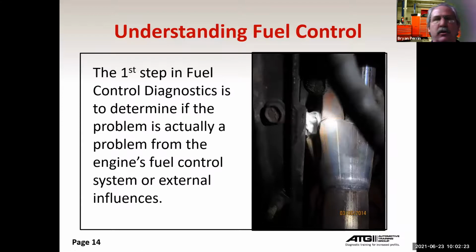and I have an adapter that goes in there. And we can see the smoke billowing out of this crack between the exhaust manifold and the engine block where you can't see. So that's how I found it on that one. And it was just a real small crack. That's what was causing the car to fail. This car had a lot of new parts on it, including a new catalytic converter, but it still wouldn't pass smog. I got it from another shop.